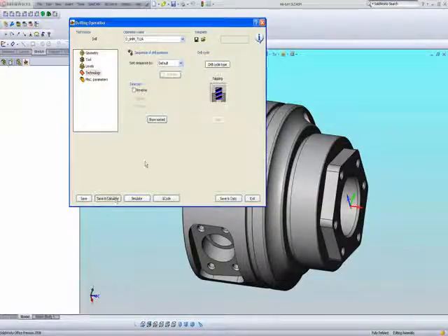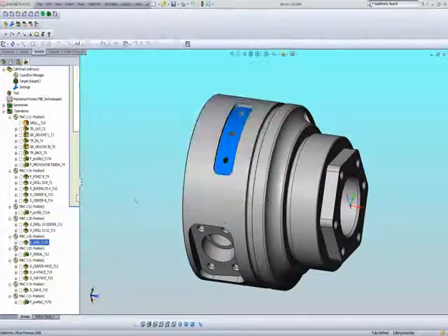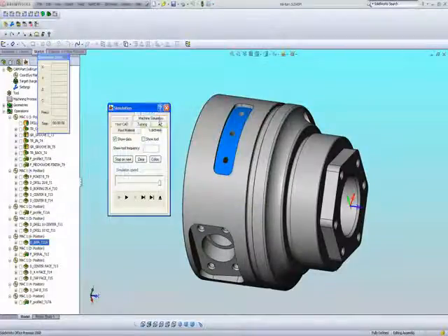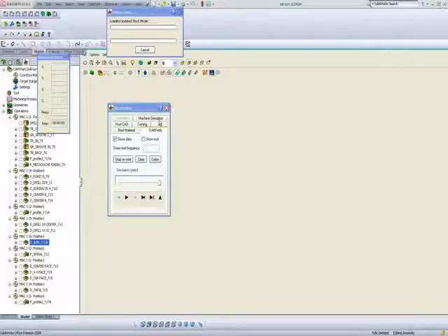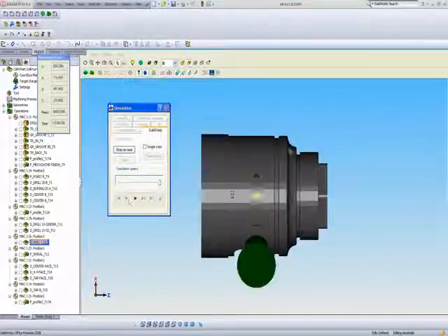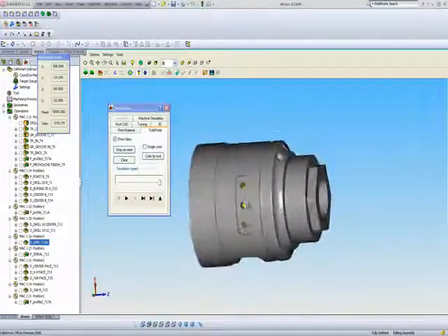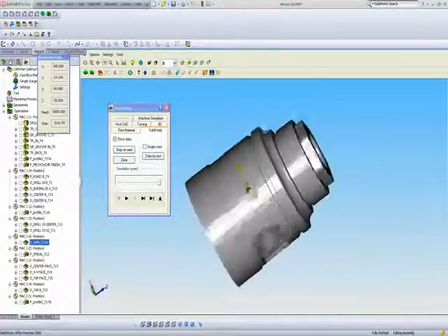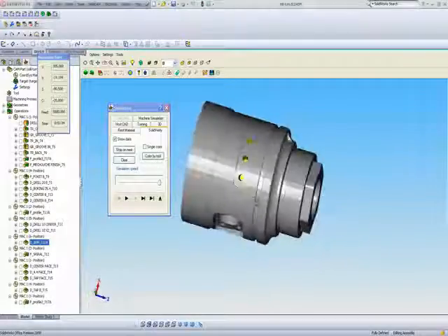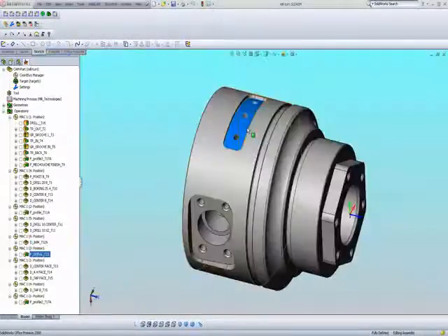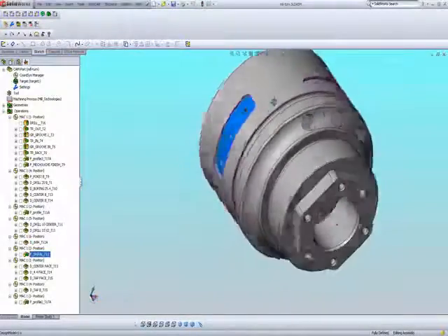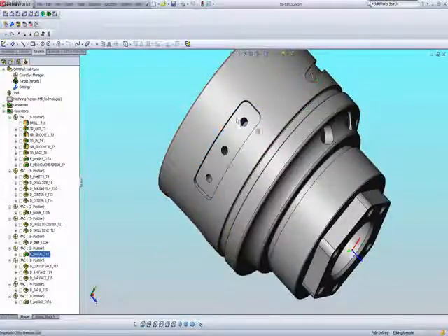and calculate, even though I make a mistake every now and then, simulate, and if I do my solid verify simulation, you'll see that all of these holes are drilled out exactly the way they're supposed to be drilled out within one operation. I now like to deal with this particular slot over here.